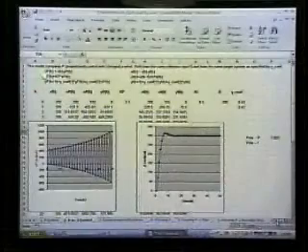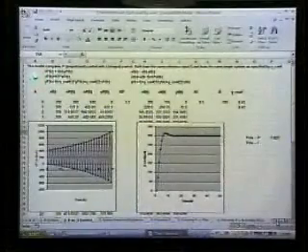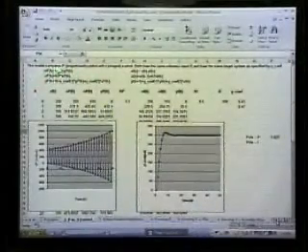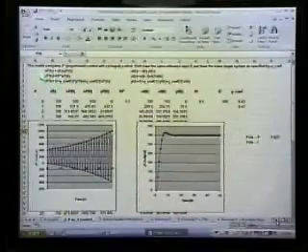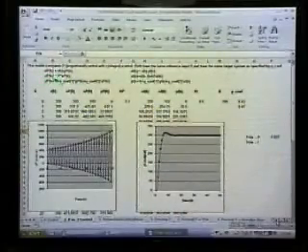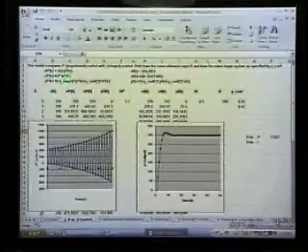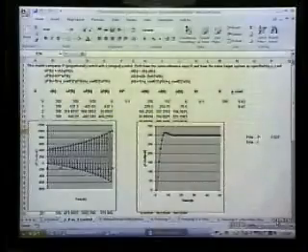Okay, so this is sort of a spreadsheet version of what we saw before. Here's the proportional controller. We see how the error is calculated. The key thing here is how the control input is calculated. It's Kp times Ep of k, because the P here is intended to be a subscript, but it's just written in the same case. And you'll see an I over here that corresponds the same way.